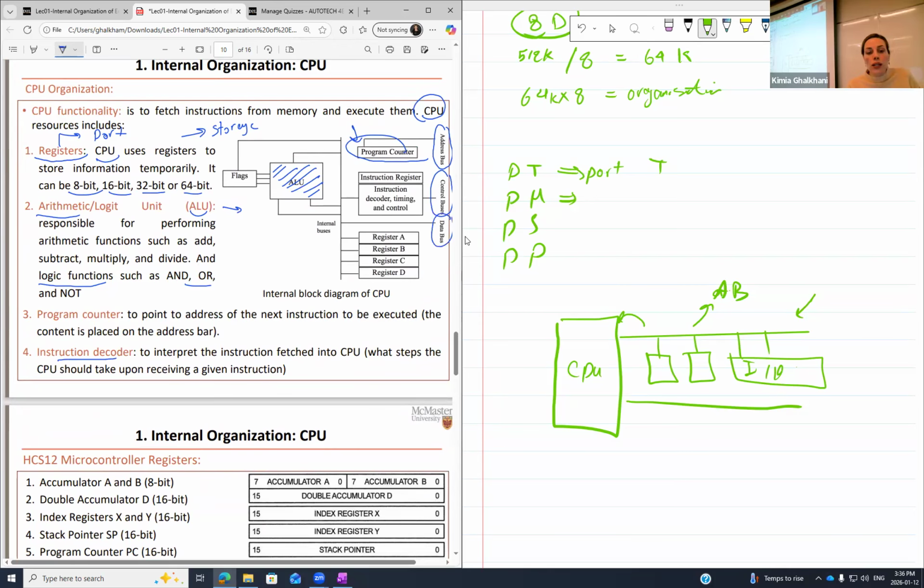And the last one, the data bus. Data bus is the one, remember again, from the same picture I just showed you. Data bus is the line of communication that can define which device is only input or only output, or is both input and output. That's where I have to define my data. That's why I say now every register or every port I have must be connected to the data bus.